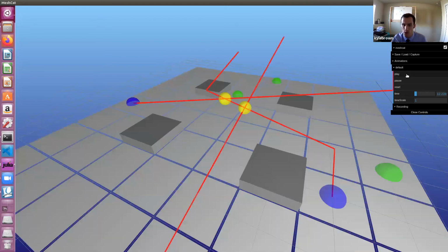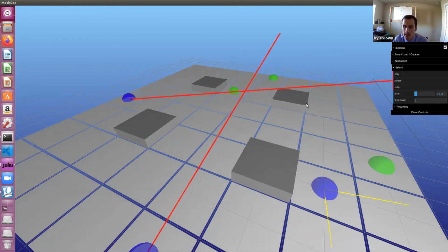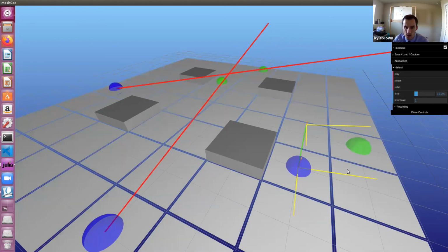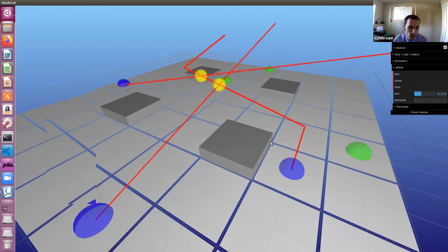So let me animate for you the search process if we plan the path with the regular A* path planning problem. So here you can see that proceeding here, A* expands a search tree of states in best first order, and states are scored according to how far they are from the goal plus how far they are from the start state. So here we see this is the path that was returned by A*. It's exactly what we just saw.